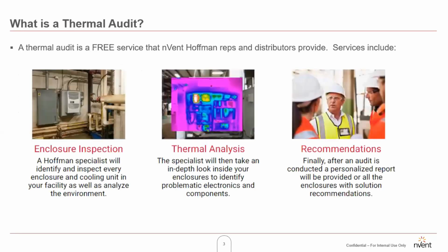So what is a thermal audit? A thermal audit is a free service that we as nVent Hoffman reps provide, as well as our distributor partners like the Reynolds Company. And it basically is divided into three parts: enclosure inspection, thermal analysis, and recommendations. For the inspection part, we'll get into more details later, what all we're inspecting and the notes that we need to take on each enclosure, but we'll take down all the necessary information in order to properly select a cooling solution. The thermal analysis, using a simple thermal imaging gun, we can get an idea of just how hot the internal temperature inside that enclosure is, identify any kind of drives that may be causing excess heat.